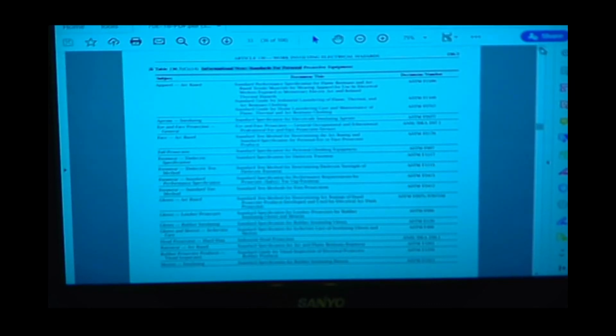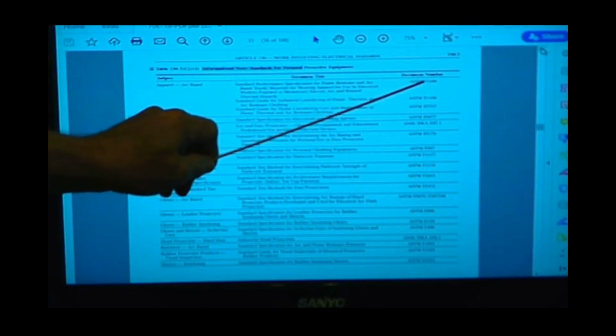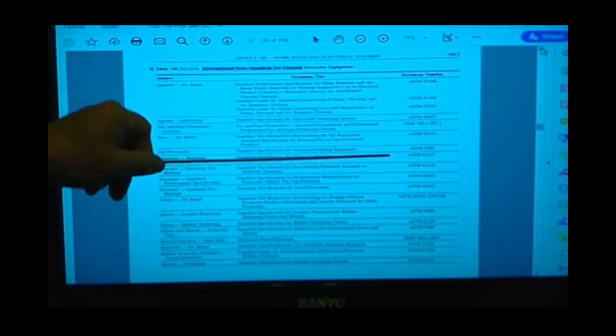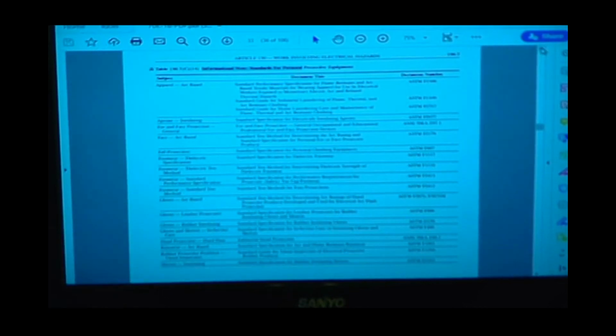Now, in today's world there's a lot of stuff coming from overseas that is counterfeit. What that means is it's probably not going to work. There's a lot of counterfeit stuff. This is why you have to look for the labels. On one of the labels on the clothing, you're going to see that ASTM 1506. If that label is on there, that clothing right there is good for arc rated for electrical workers. If that label is not on there, it is not for use for electrical workers. It's pretty straightforward. So you really should get to know what a lot of the standards are for the different types of PPE used, because there is so much counterfeit on the market today.